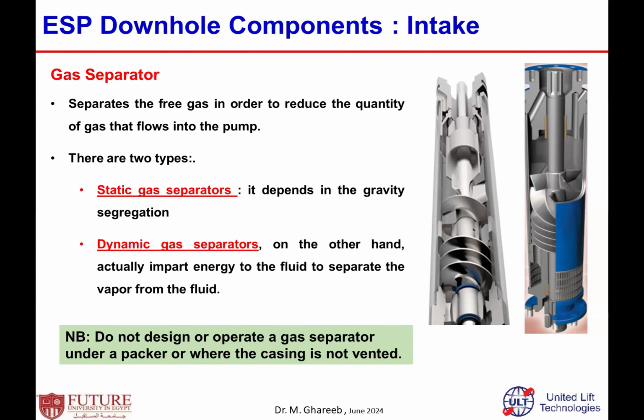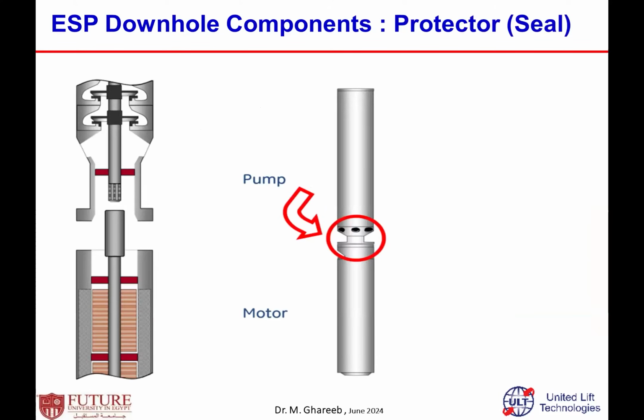Another important downhole component is called protectors, and some people call it a seal or protector. What is the seal and what are protectors? Remember, we have downhole pumps, and below the pump we have the intake, and this pump you have to run with motors. If I connect the motor to the intake of the pump immediately, what will happen in this case? The fluids will enter the pump, and for sure will enter the motor, and these electric motors can be damaged.